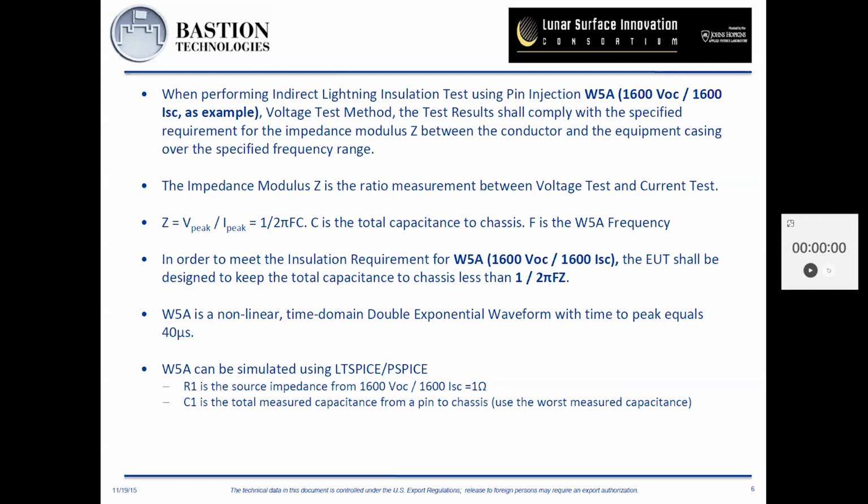That total capacitance includes parasitic capacitance and also any capacitance used for filtering common mode noise, mainly what we call Y capacitors, from the inputs of the power lines to chassis. If that capacitance is very high, that can create a lot of problems, because this lightning waveform finds that capacitance a favorable path to wreak havoc in the aircraft. Okay, next slide, please.